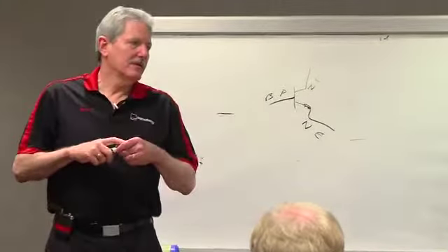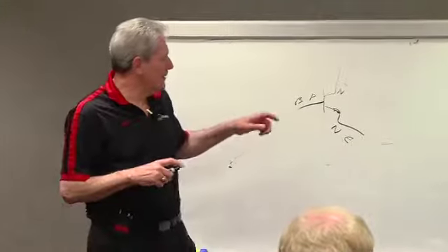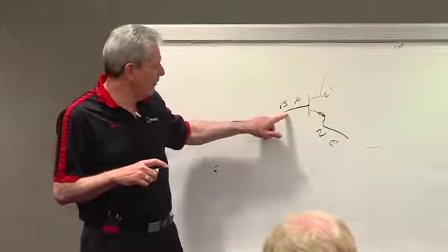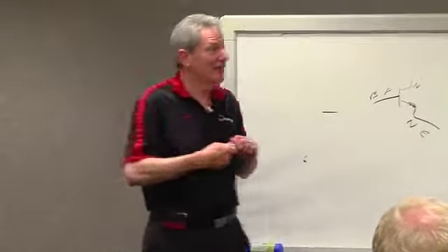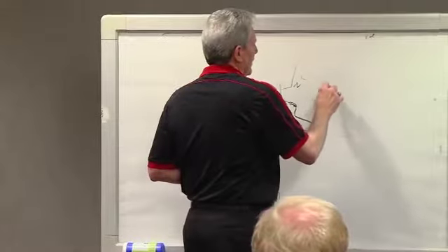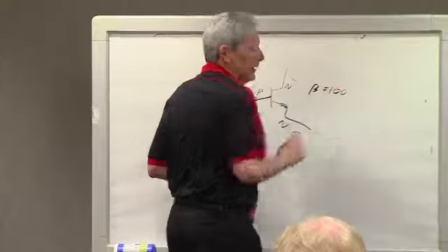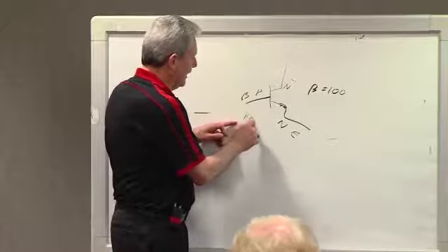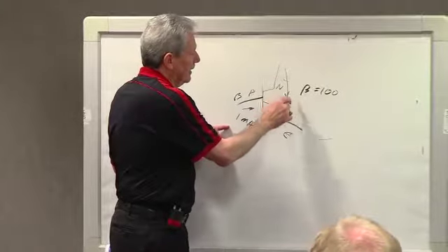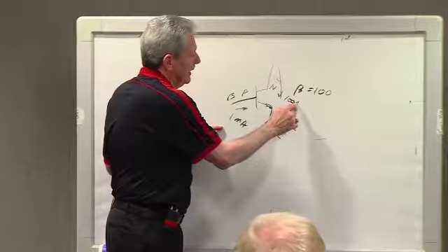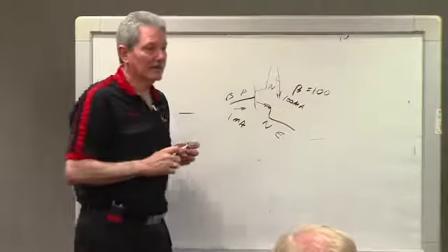The way this works, a real easy model, is you have charge carriers that go from the base to the emitter. And as they go, they take 100 of their buddies from the collector. That beta in this case is 100. So if I put 1 milliamp in the base, I get 100 milliamps in the collector.